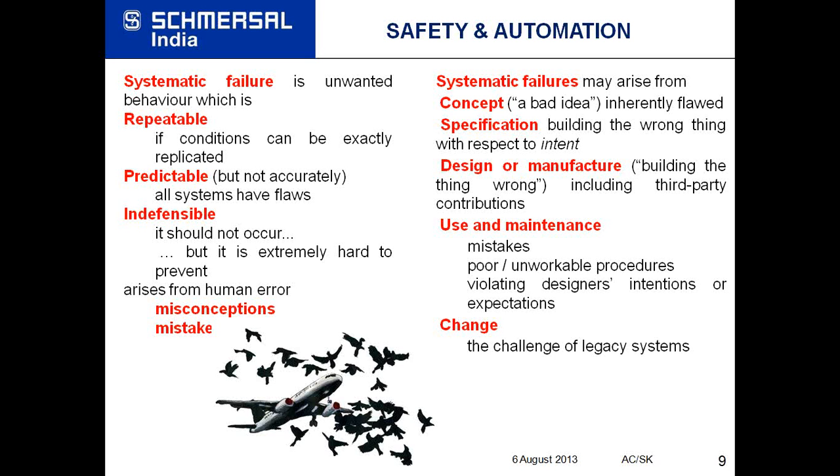Use and maintenance, like improper training or procedures, or violating the designer's intentions, like when a designer wants a machine to be operated in a certain fashion, but the operators operate it in a different fashion. Then also the changes, the challenge of the legacy system when you implement safety or automation on an older system, because of those changes also systematic failures may occur. Okay.